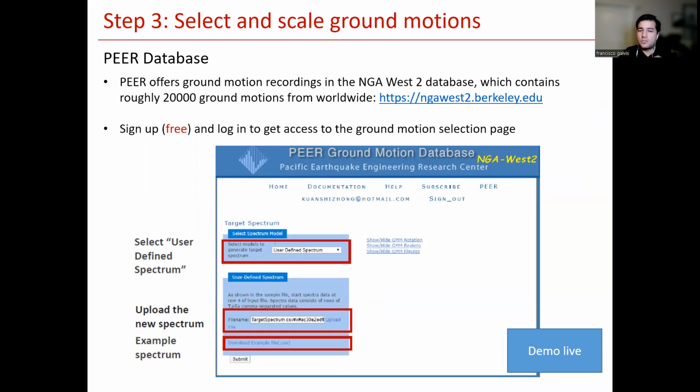That processing, in general terms, is basically taking the raw data and applying some corrections, like filtering really high and really low frequencies that are not really frequencies from the ground motions, but noise on the signal, and maybe doing some baseline corrections if the instrument wasn't centered at 0, so forcing it to be centered on 0, and applying the constants of the instrument to go from whatever electrical measure it had to acceleration.